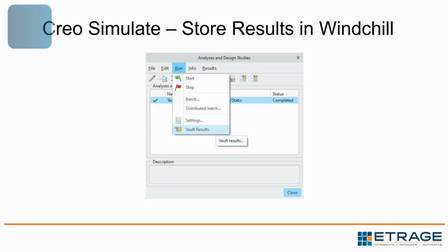number one, you do want to use a unique name, because that's a characteristic of Windchill, in that it enforces file uniqueness. And so the default analysis name being Analysis1 in Creo Simulate wouldn't fly if everyone saves analyses called Analysis1 and all want to check it into Windchill. It will throw up an error at some point.